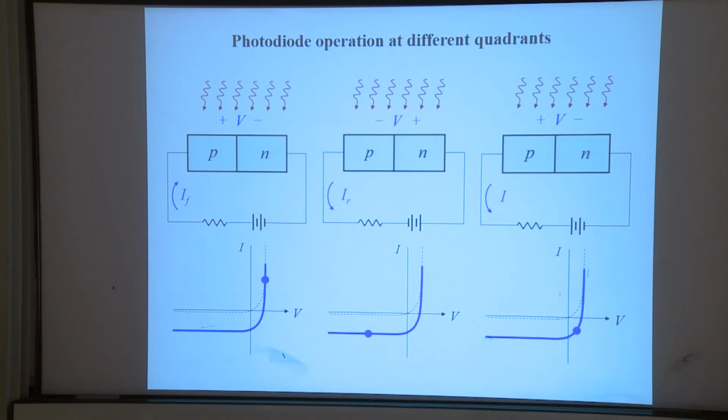So what will this be used for? Anybody think about this application? It is not a function of voltage, but only a function of irradiance. The power of a solar panel? Sensor, yes. You only need to bias this PN junction, then it can measure the irradiance for you.